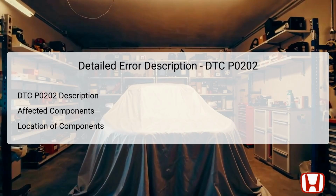injection process. The number 2 fuel injector is located on the engine's intake manifold and is crucial for delivering fuel at the right moment during the combustion cycle. If there's a failure in any of these components or their connections, it can trigger the P0202 code. The diagnosed issue needs to be addressed promptly to prevent further engine damage or performance issues.